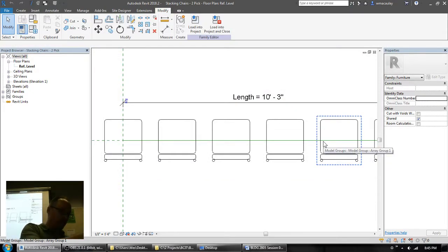Going over to parking stalls, page 8 rather, page 8. So this is a second type array, just like we discussed. So you get the parking stall family, you load it into this generic model line-based family, and you go to town. So you guys know how to nest a family. That's all that you would do.